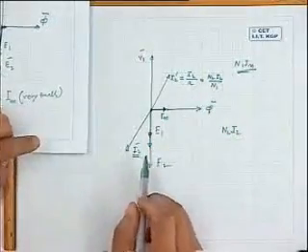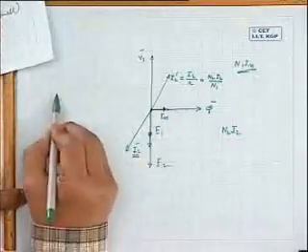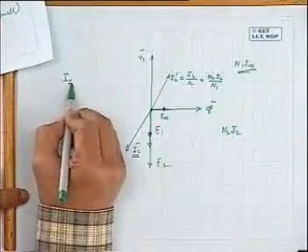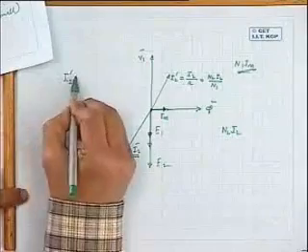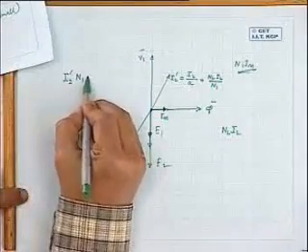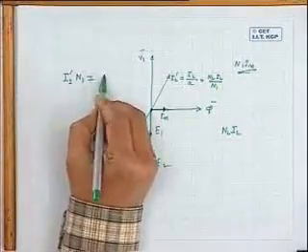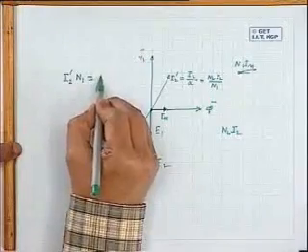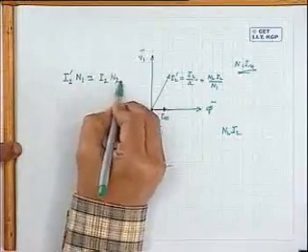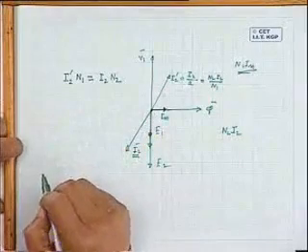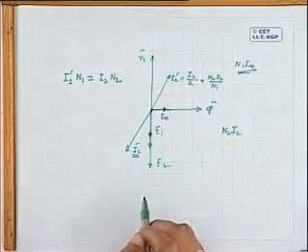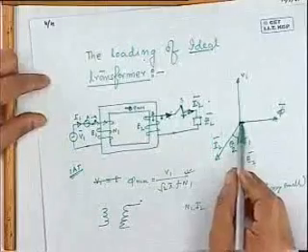That is N2 I2 by N1. That is, the additional current the primary will draw, the magnitude of which should be such that I2 dashed N1 will be equal to I2 N2. So under loaded condition, what will be your ammeter reading?